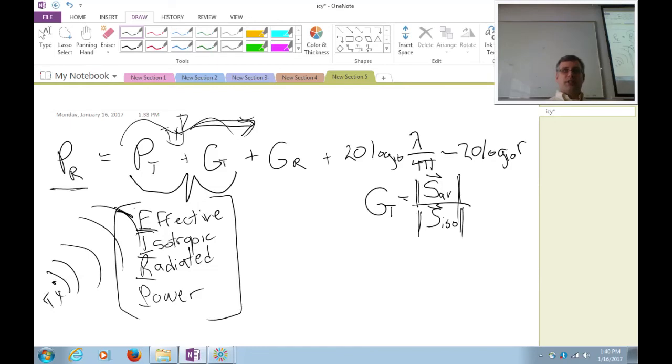How much power does it take out of the plane wave? Well, it depends on how big the cookie cutter is, how big the cross-sectional area. We say an antenna has an electromagnetic aperture. We measure it in meters squared. It's an area over which it approximately gathers power.